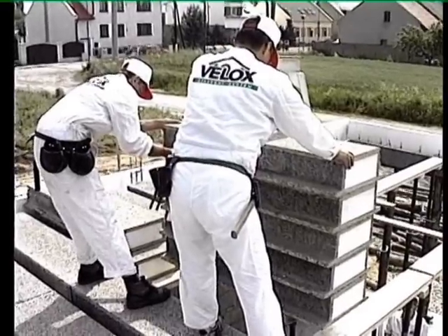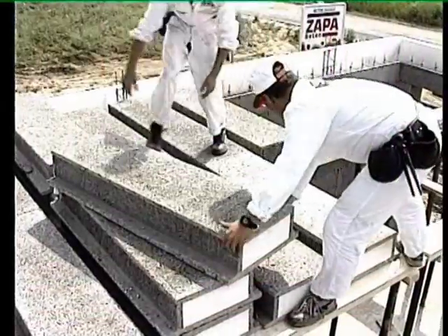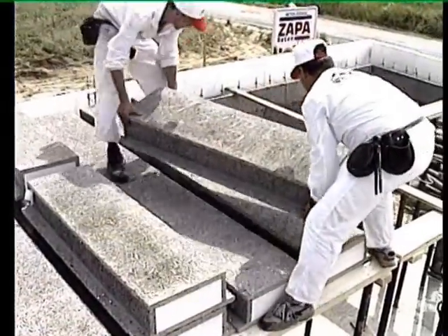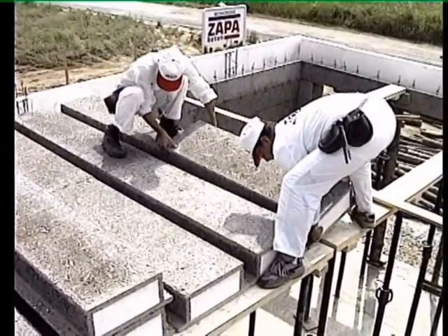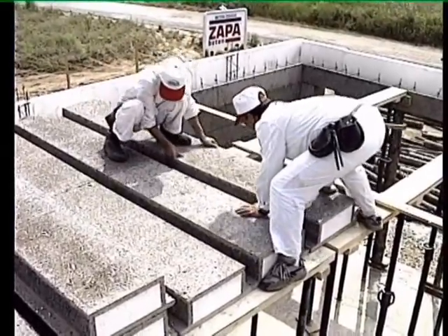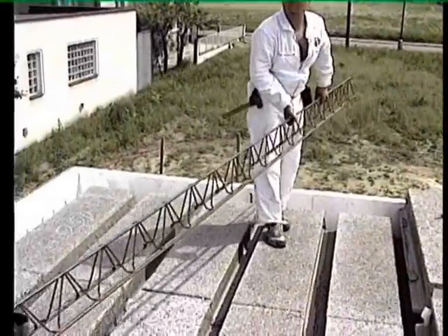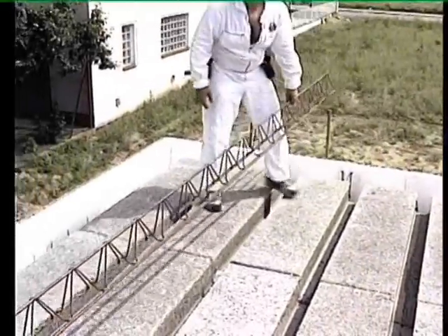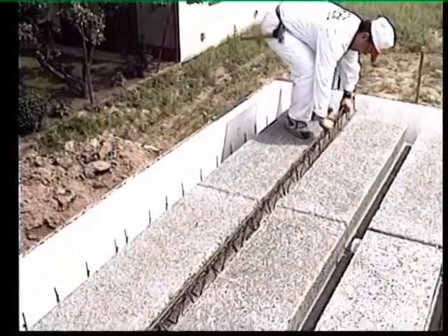Ceiling components in lengths of up to 2,000 millimeters are made from boards. These form boarding for a monolithic ribbed ceiling with ribs that are 120 millimeters wide, spaced at 500 millimeters, and with a variable cross-section height. Ceiling reinforcement is chosen based on span and load in connection with the effective height of the cross-section.